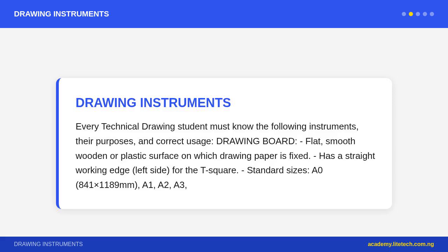How to use: 1. Place center mark of protractor on vertex of angle. 2. Align the baseline, straight edge, along one line. 3. Read where the other line falls on the degree scale. Protractors are for measuring only. Use set squares and compass for constructing angles precisely.